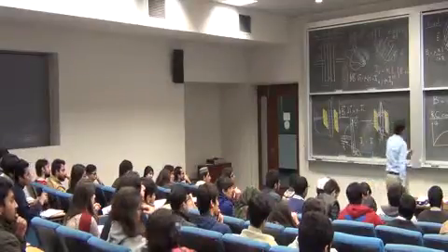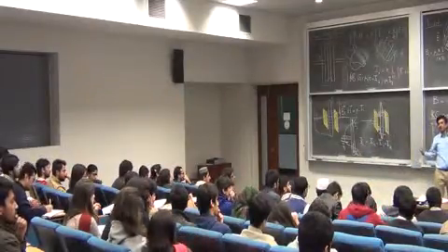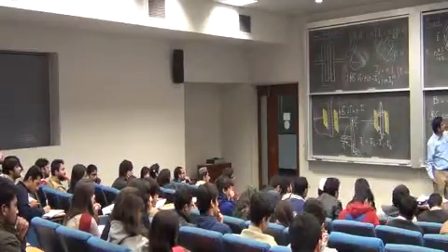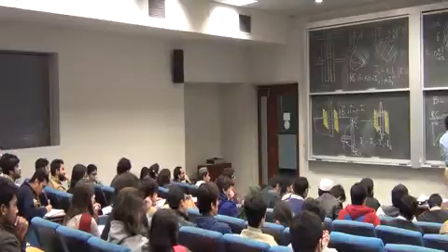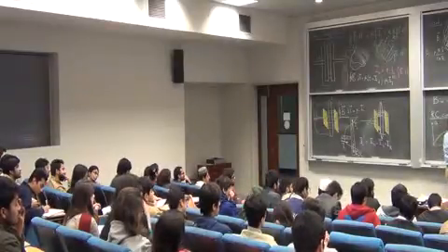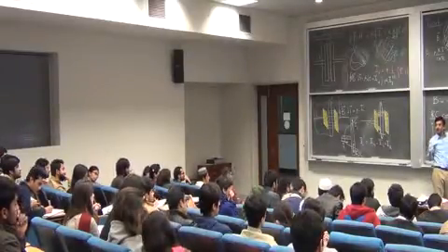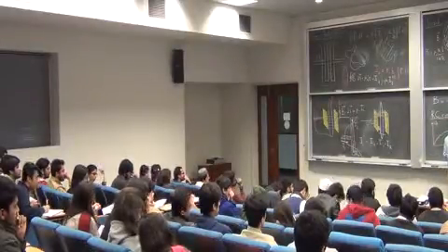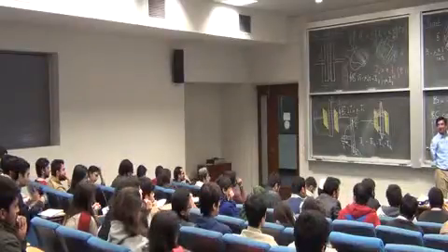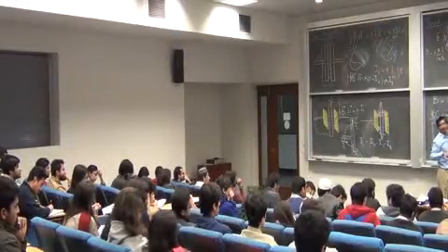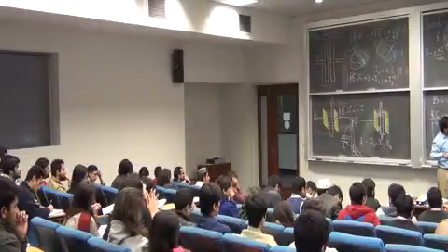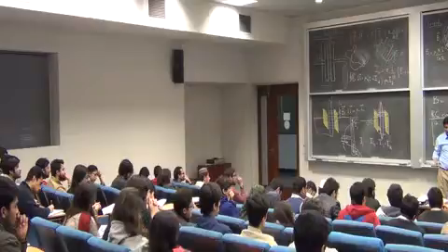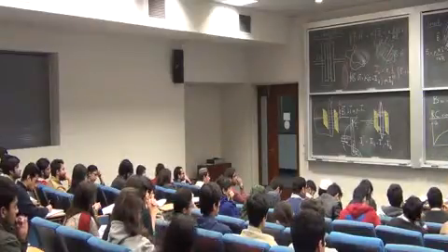Exactly. Initially, the capacitor is uncharged, it has no fringe electric field. So it's as if the capacitor is not there. All the electric field is inside the wires. So I close the switch, all the electric field is inside the wires. There is no fringe field here because it hasn't built up any charge. As soon as it builds up charge, it produces a fringe electric field that opposes the electric field produced by the surface charges on this wire. So the net electric field inside these wires decreases. When the net electric field decreases, the current drops. So that's why the current drops exponentially.